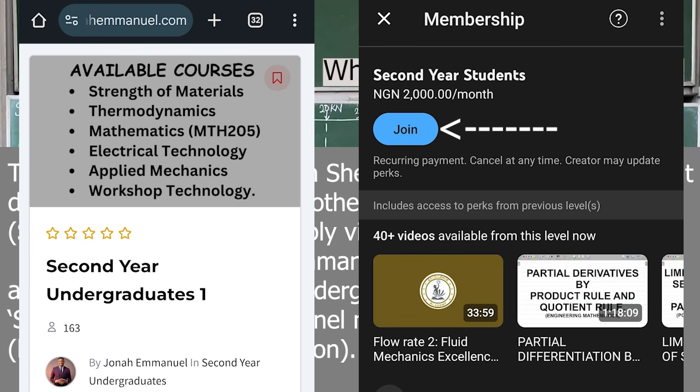The second condition is called the point of contraflexion. The position of maximum bending moment is where the shear force cuts the x-axis. The point of contraflexion occurs where the bending moment diagram cuts the x-axis. For this case here, observe that the bending moment did not cut the x-axis. It was all above, it didn't cut this. So in this question here, there is no point of contraflexion.